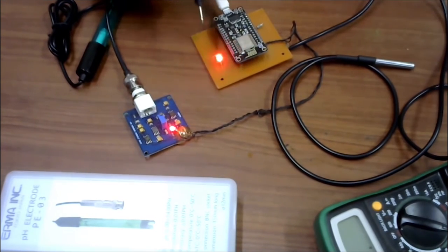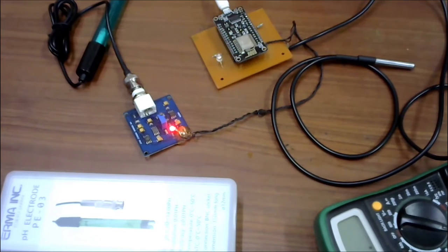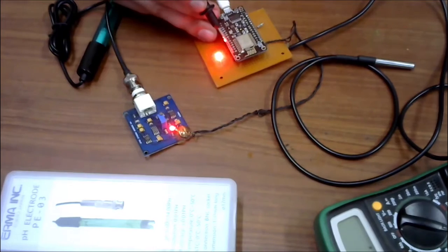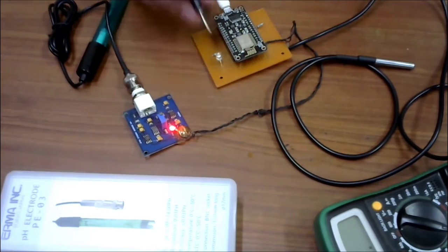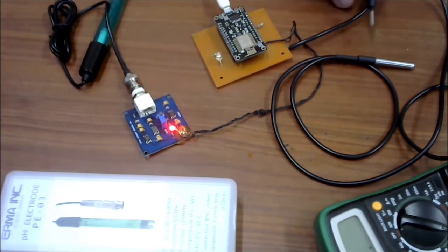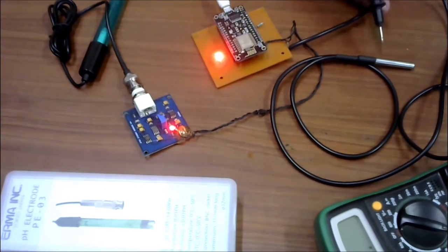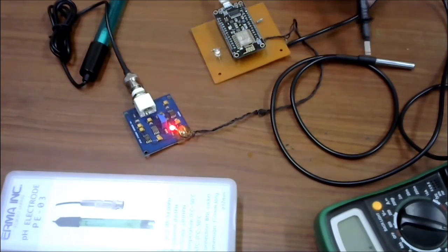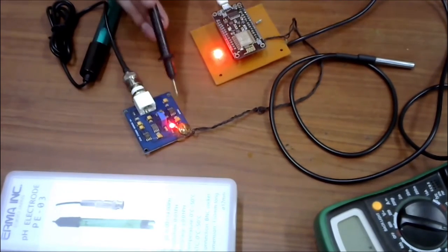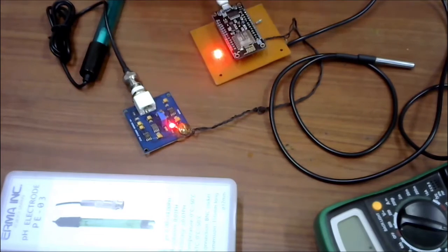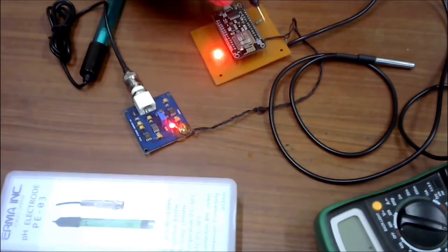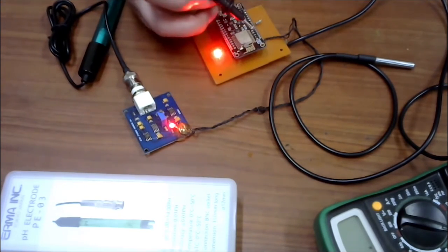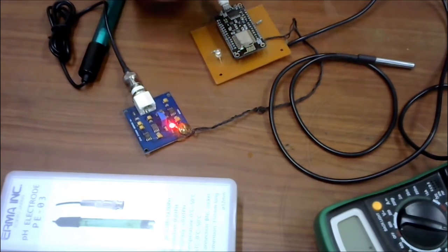Generally, in digital communication, we have one ground as reference and it is 2 wire communication. But here, it's 1 wire communication, that is a single wire is used to send the data stream in bits. The temperature readings from the temperature sensor are sent to the pin D3 of the node MCU. In node MCU, we have only one analog pin. So if we have to add some more sensors, then we will have to use an analog multiplexer.